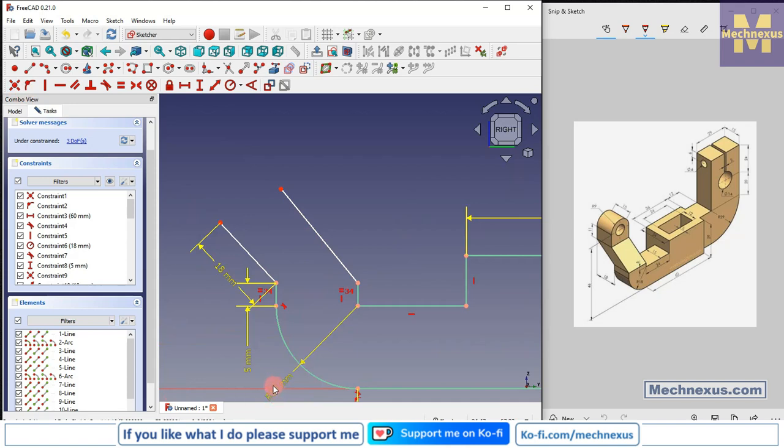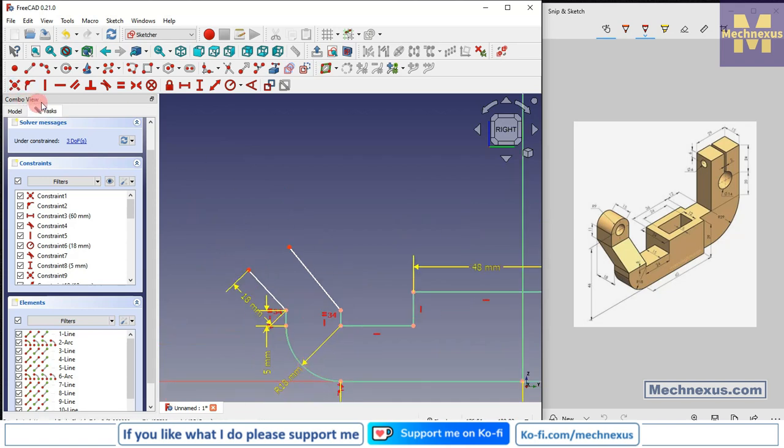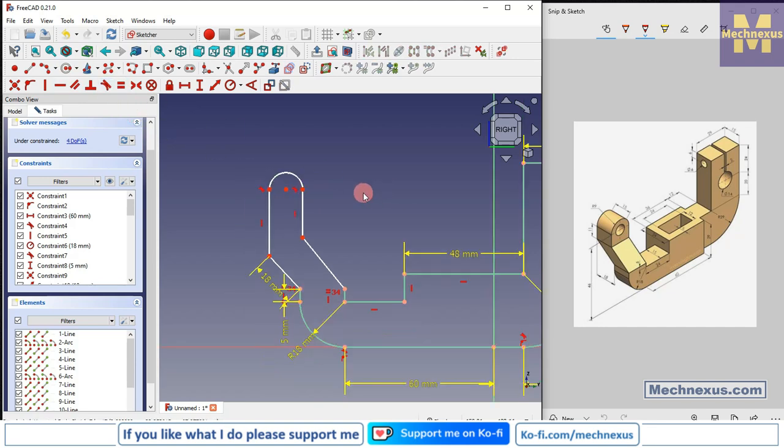And now select the line tool, create a vertical line, and now select a 3-point arc and create an arc. Now add the tangency, select this and add the tangency.